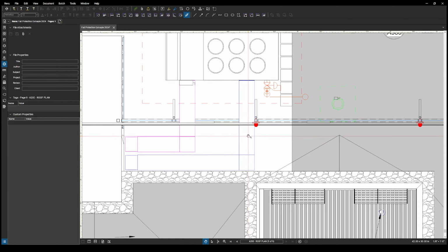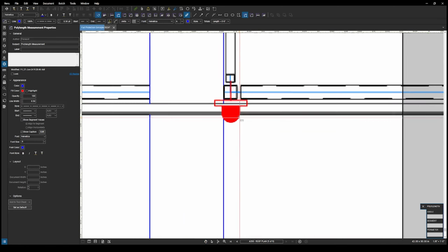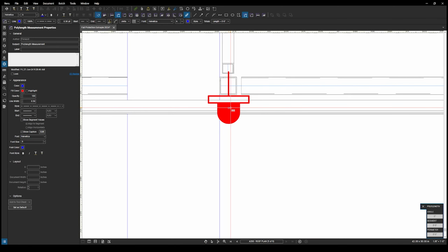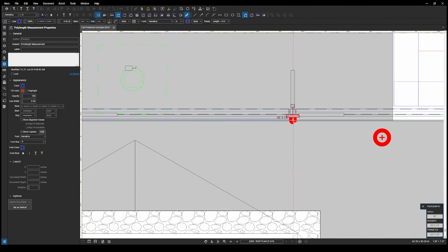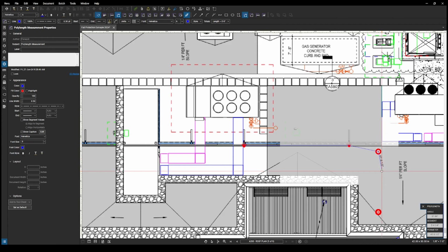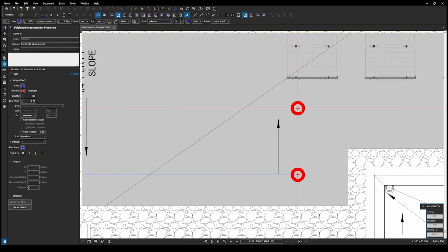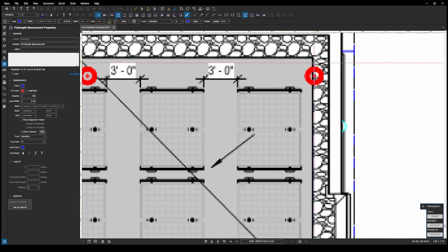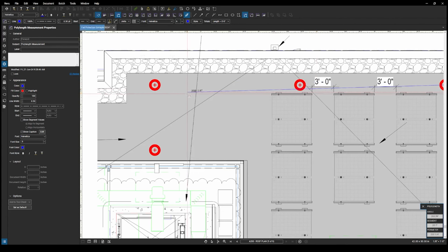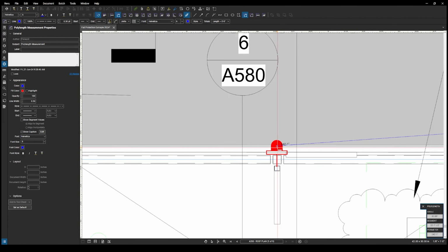Have one corner right here. Then we're going to come all the way up. Snap that on. Put it onto this roof anchor. And, again, there needs to be 18 inches away from any actual roofing element for safety. And so that way it allows for proper weatherproofing and things like that. So we're actually going to divert the cable. This one goes fine because it's in a straight line.